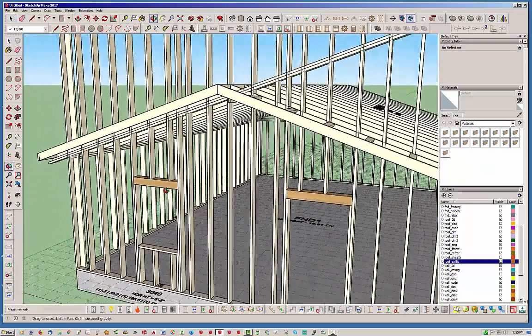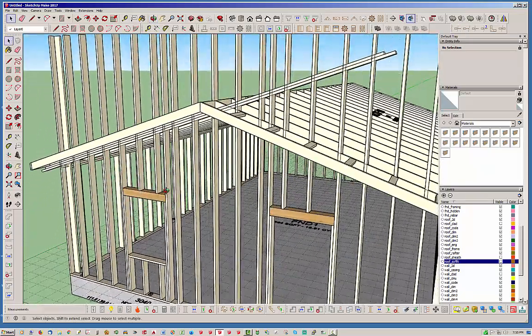So really easy. What you want to do is grab this toolbar from the Medeek tools, and this is actually part of the Truss plugin. This trim tool comes in real handy, and it can be used not only for the Truss plugin but also for geometry from the wall plugin, foundation plugin, or any other geometry for that matter.